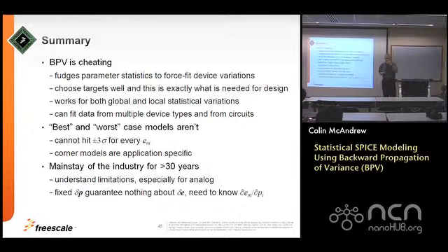The main place where I think there are issues with the normal distribution is particularly for memory design. The reason for that is if you look at data, what tends to happen is they have higher tails than you normally get from a Gaussian distribution, and at present we don't handle that. So the only thing that's non-Gaussian that we handle is log normal, but you don't explicitly tell it. You actually have to set up the model file so that it has the exponential mapping and it does that for you.